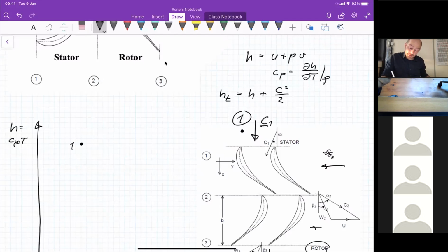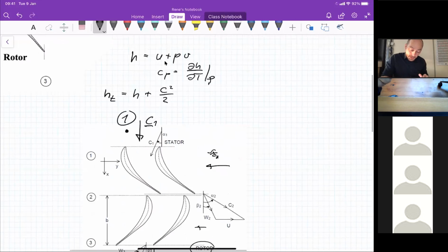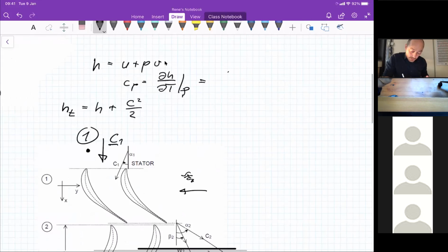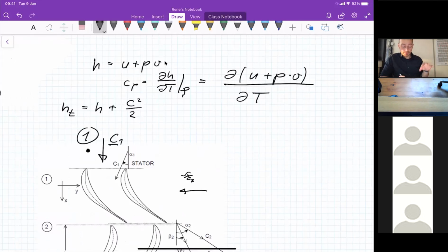And then, in fact, what happened in the beginning is that we didn't get such an equation, but we got the partial derivative of the internal energy plus the pressure times the specific volume, the derivative of this term with respect to temperature, but along an isobar, right? Along an isobar. And so that I don't need to write U plus PV all the time, because it's tiring, we have just introduced a new quantity, which we call enthalpy, okay?